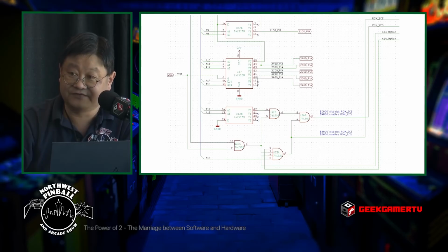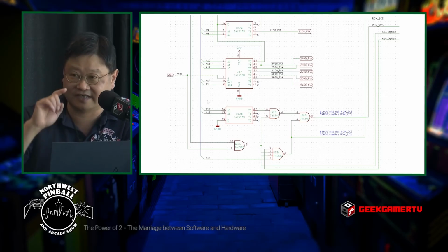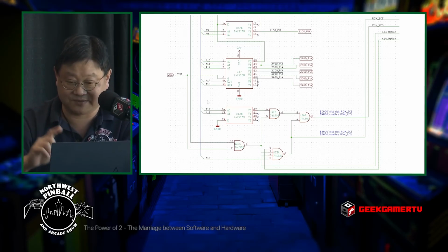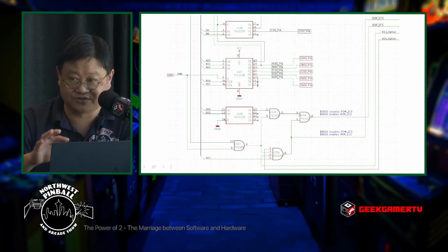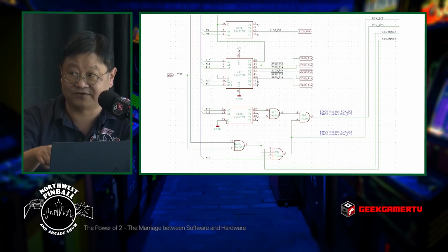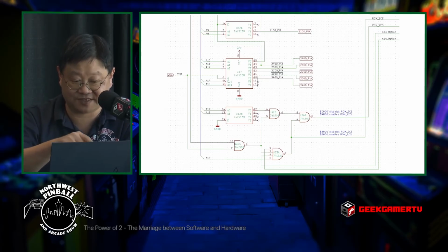So this 14 and 15 will deal with U26, and I'll show you how it gets U26 to be active. This is an enable bit. For this particular logical unit, it's a 2 to 4 decoder. The enable bit is tied to ground, which means this logical unit is always active because it's E with a bar over it. So it's always active when it's tied to ground.